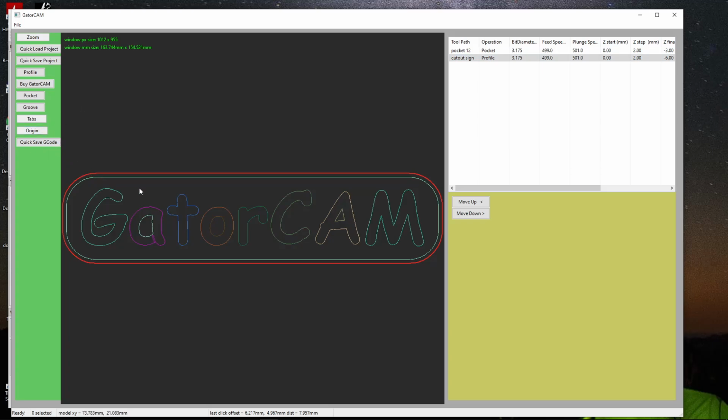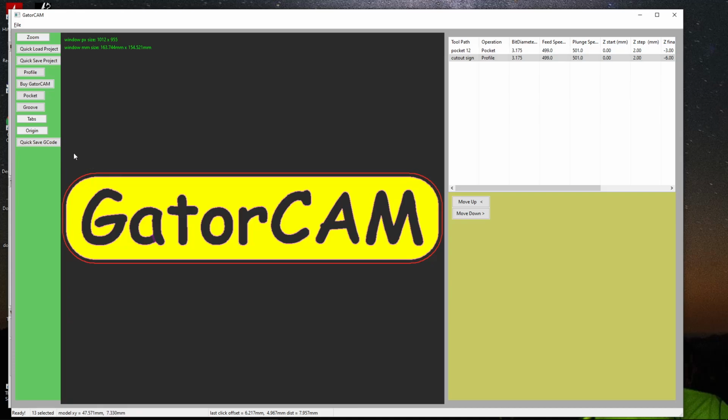So the origin, when you select an object and you go to origin, you can center the origin with the object, the bottom right, the bottom left, top left, etc. So I like using the bottom left on my CNC machine, and I usually change the offset to half a bit width, so that's like 1.8 millimeters. I like to maximize the use of my material. So I want the bit to start here.